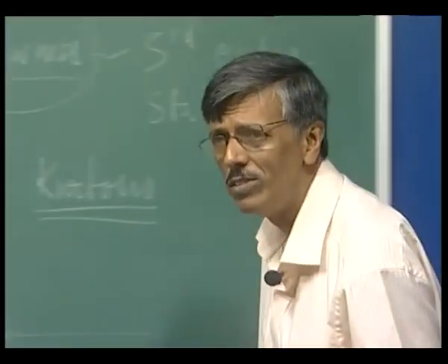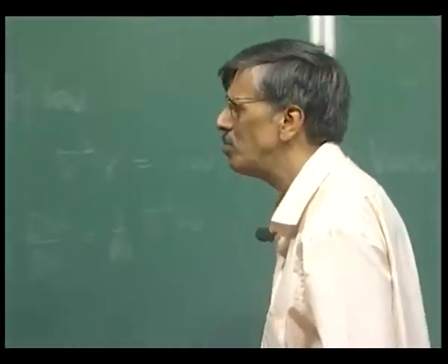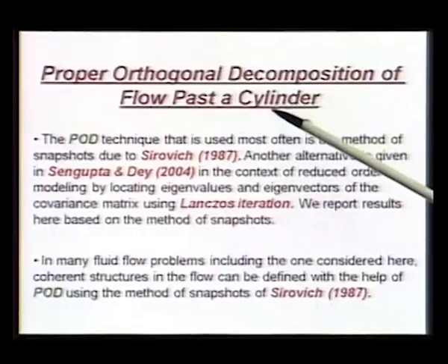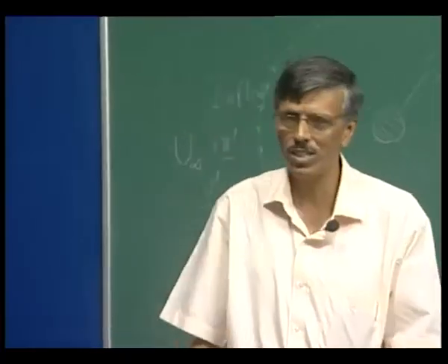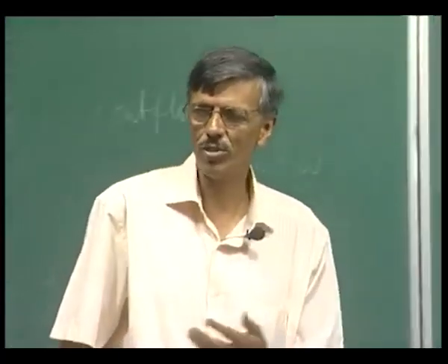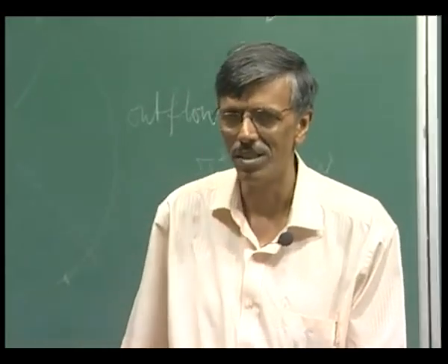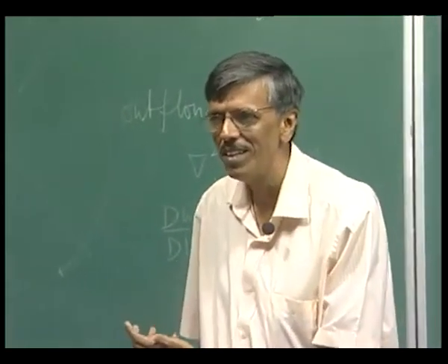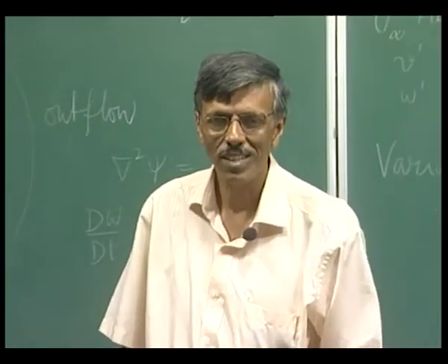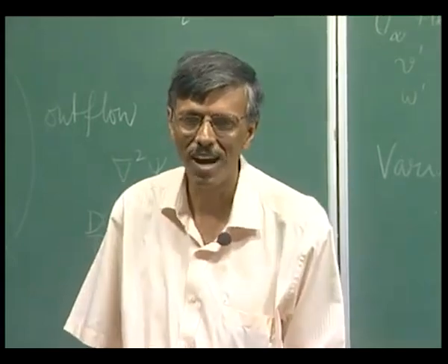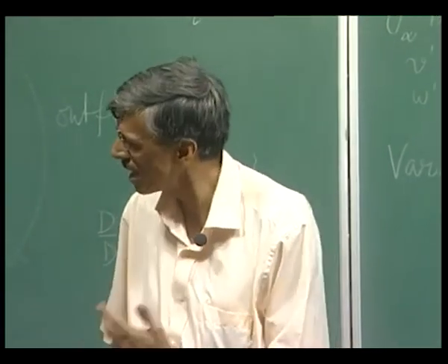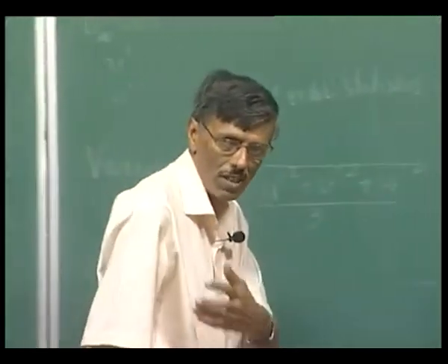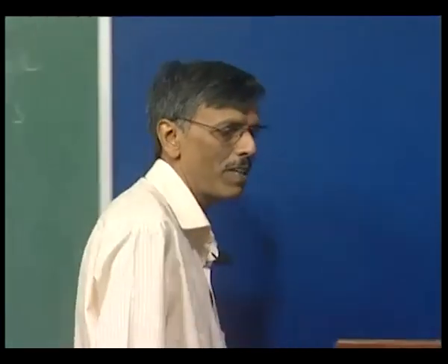Any unsteady flow, we can make use of it, and in fact that is what we are trying to do now, because we are going to use this POD technique to study instability of flow, and during instability we have already seen that it is going to be a space time dependent phenomenon. So, can we use POD for studying instability? That was the question that we have been asking for the last few years. And I think we have now come to a state where we have been able to develop a very coherent picture of it, and we'll see some of these results.